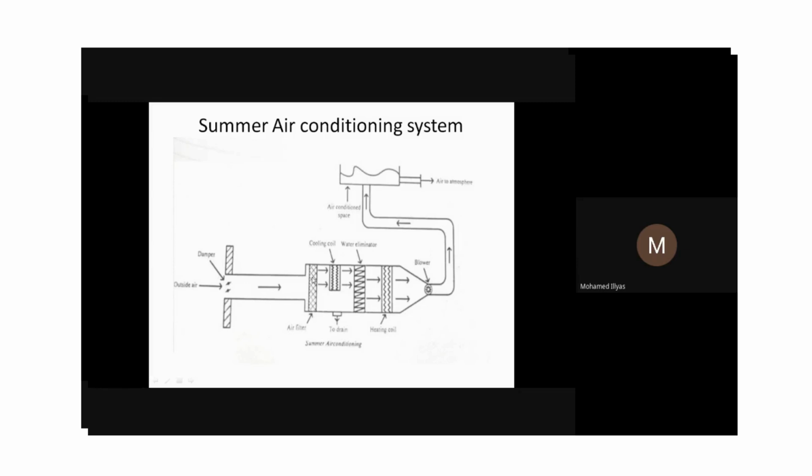You see it here, the pressure remains constant when it reaches its dew point temperature. Right, so actually what will happen? Theoretically, we assume the pressure remains constant, but practically some pressure drop will be there. The water vapor present in the air will start to condense. This is the process of removing the moisture content in the air. Here the temperature will also remain constant when the phase change occurs.